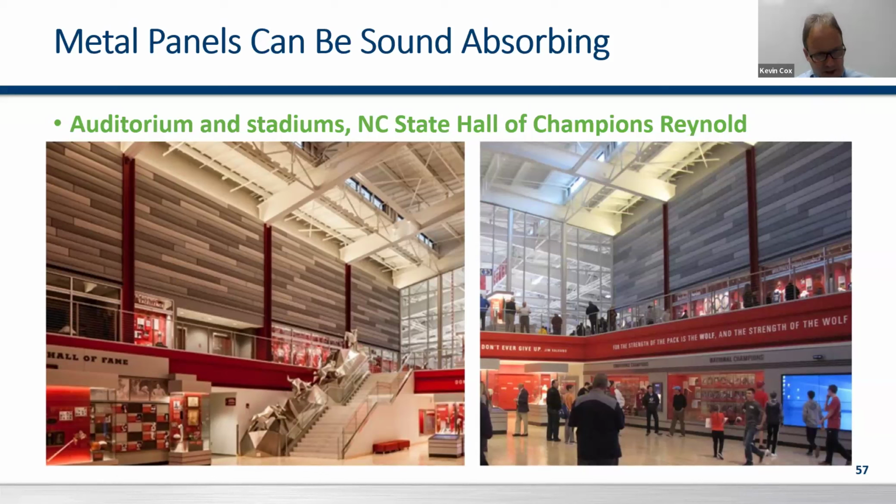Well, no one really thought about the acoustics, so when they went to use it, it was so echoic. They had an RT60, or a reverb time of about 5 or 6 seconds, that they couldn't understand what was being said. The solution was those tricolored, micro-perforated, factory-folded edges sound panels on the side with a 2-inch sound bat on a girt. Generally, for an auditorium area, you want to get the reverb time down under 2 seconds or so. They got it to about 2.3, but at least to a place where they could use that space for its designed intent.